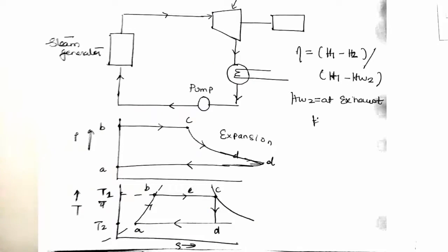Again, this steam or gas at a high temperature and a high pressure hits the turbine blades, and it causes the conversion of the pressure energy to mechanical energy. It causes expansion on the turbine blades. As it expands, the pressure is reduced as it acts upon the turbine blades.